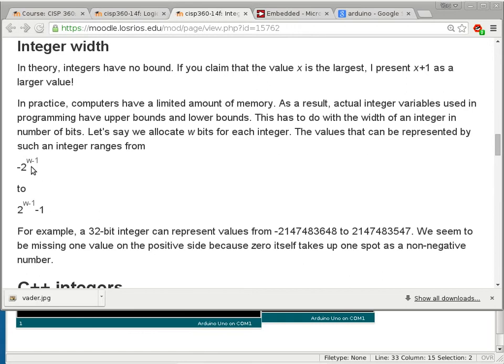It also matters where you shove the information into the 8-bit. Well, it has to do with the implied width of an integer. We talked about this a little bit on Monday. The implied width of an integer depends on the target platform. So when you're dealing with a PC like these, the implied width is usually 32 or 64. But when you're cross-compiling to an AVR platform, it is only 16. As a result, programs that need a wider integer would not work anymore because the width is now changed.